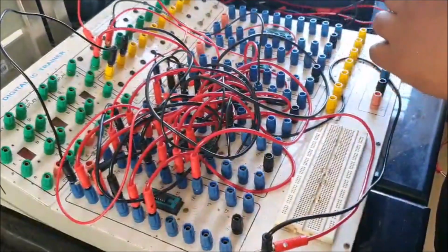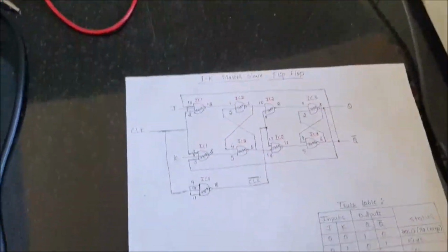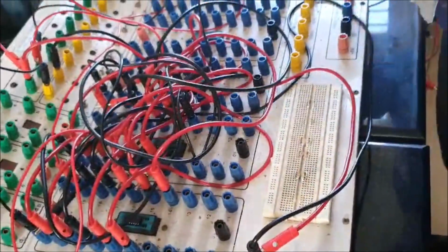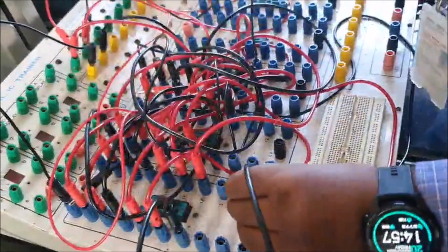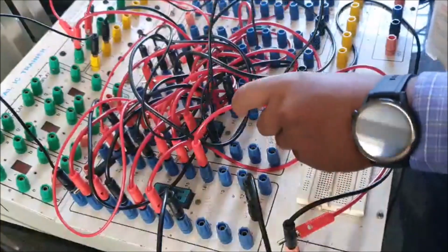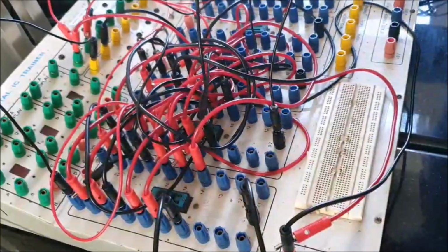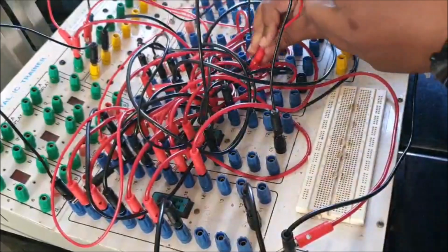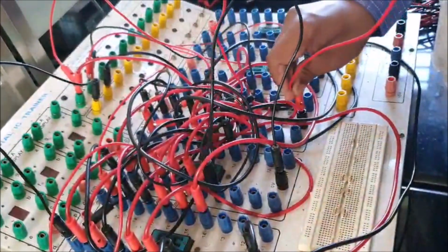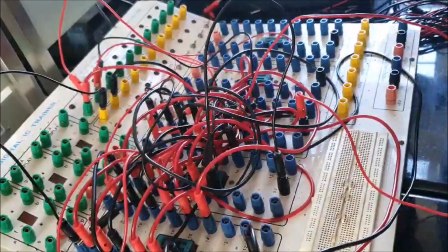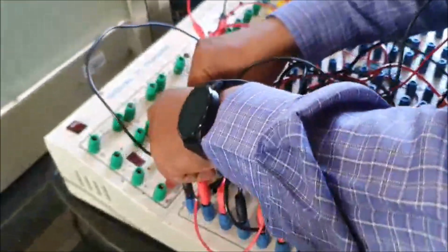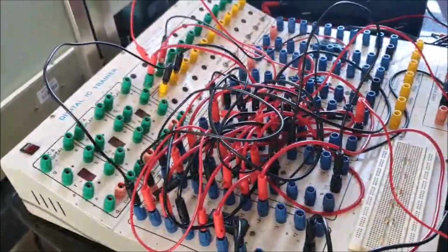Okay, so next what I need to do is I have not done the VCC and ground connection. In all these three ICs, the 7th pin is connected to ground and the 14th pin should be connected to VCC. Now for the third IC, I will connect one end of the patch cord to the 7th pin, another end is connected to ground. Now I need to do the VCC connection. So I will take up one patch cord, the 14th pin is connected to the plus VCC in all the three ICs.